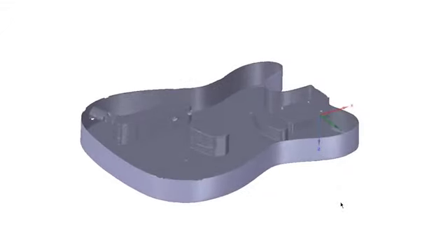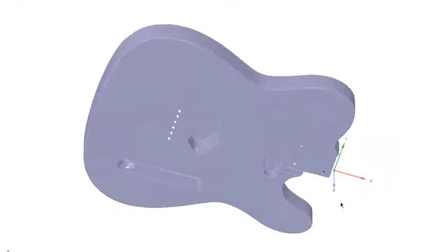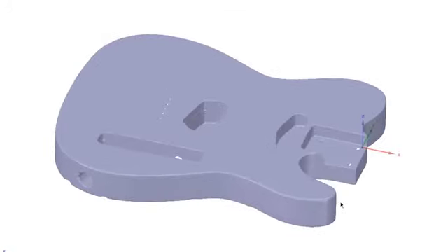We didn't scan the bottom of the part, but that is what's nice about a modeling over top of a mesh workflow: I don't have to have all that information. I can infer the rest of it based on the design and the designer's ability to redesign the part.